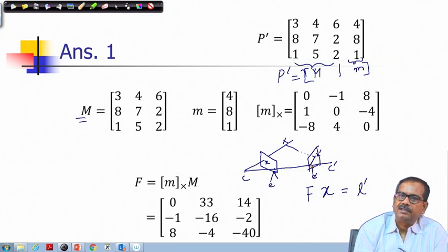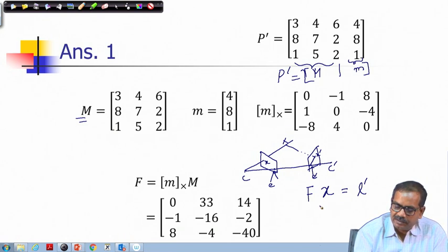So, as we have seen earlier also, this is a case of singularity. You cannot form a line just by connecting the same point to itself. You cannot define a line using a single point. So, that is why, this is a geometric constraint that we understand, but mathematically this constraint is expressed in this form.